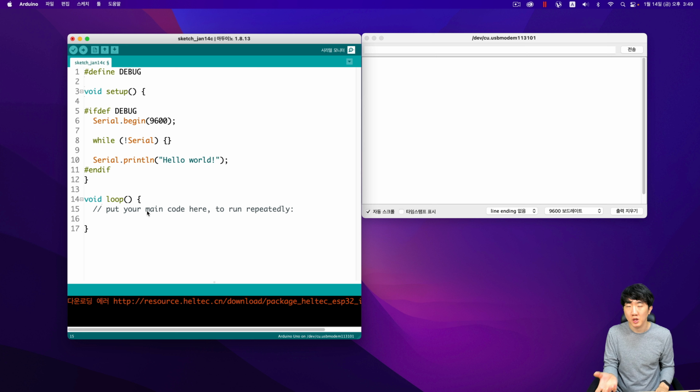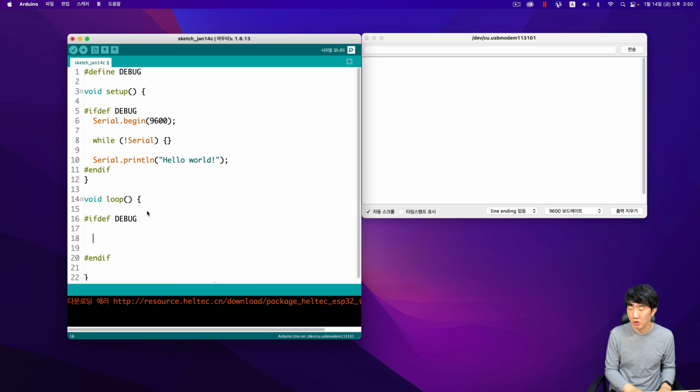Of course, I could input that color into the code each time, but that would take a long time to verify and upload. Instead, I can write the code so that the Arduino receives the RGB values in real time via serial communication and reflects those values on the RGB LED. So what you can use is something called parseInt, and I'll show you an example. Similarly, let's assume that in this particular scenario, we can observe that this is one of the debugging processes. So here we have several steps, such as if, debug, and if, which the process involves debugging and checking.